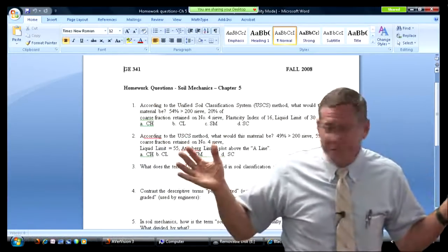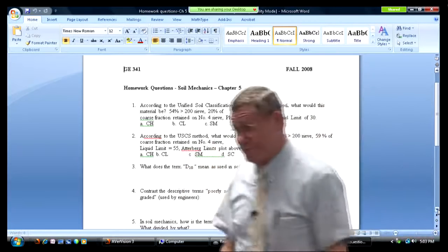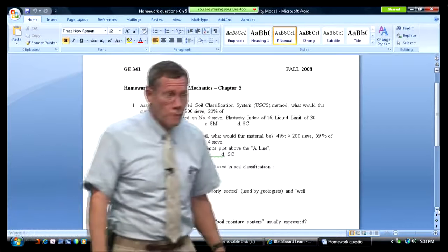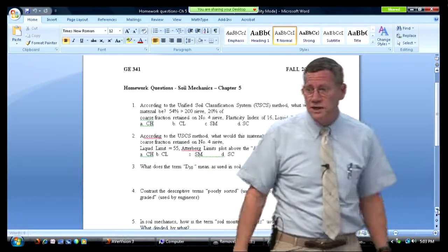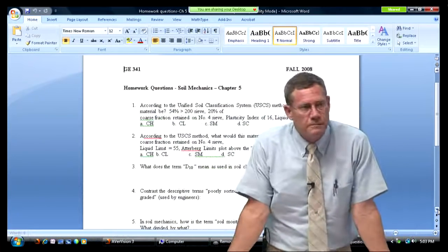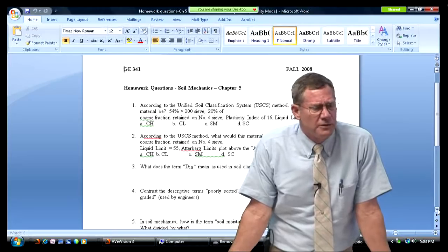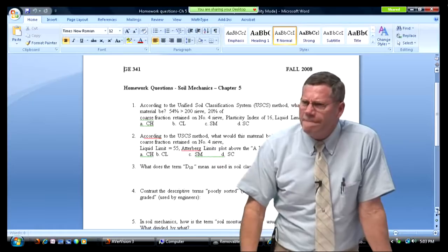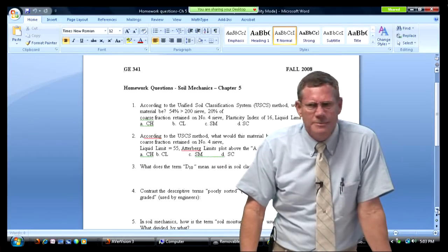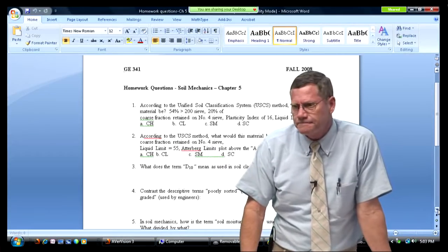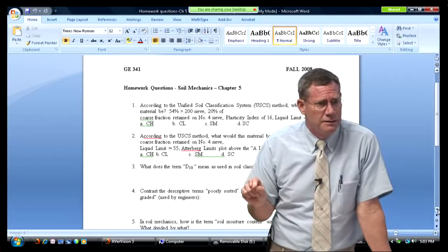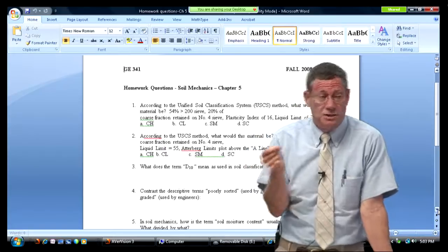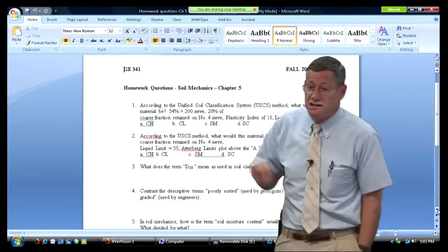No! It's not there. It's what happened with the San Jacinto levee failure, California. The Corps project had a 25% flood against it. It disappeared. 25% of the design flow. Did you miss the mark by a little bit? I'd say someone missed the mark by a whole lot there. And the problem was that channel didn't have the material. It was spec'd. There was a standard specification in the contract document. It didn't exist out there.